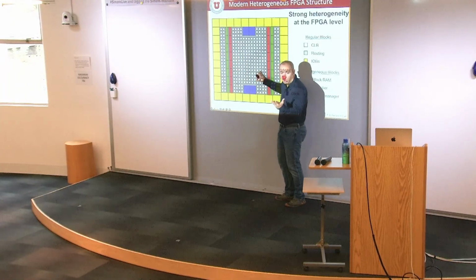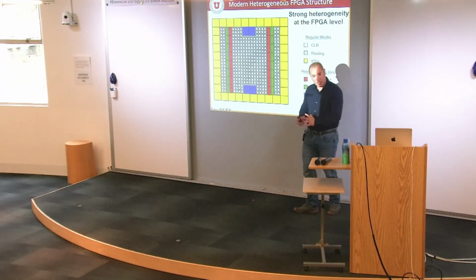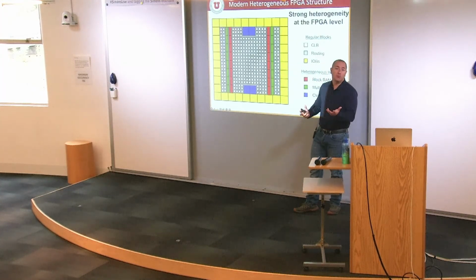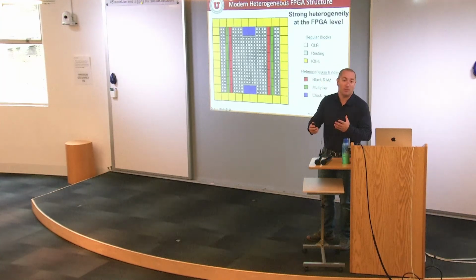So what you just mentioned is that we can kind of treat the LUT as RAM, but here the block RAM is kind of a denser version, like if you think of a memory macro. Yes. Everything in these blocks can be programmed to be logic functions or memory as well. We call them LUT RAMs. But as you can imagine, they're not very dense because they do other stuff, right? So for something where you'll need good density, so cheaper memory, essentially, you will rely on the actual BRAMs, block RAMs. Okay? Okay, thank you.